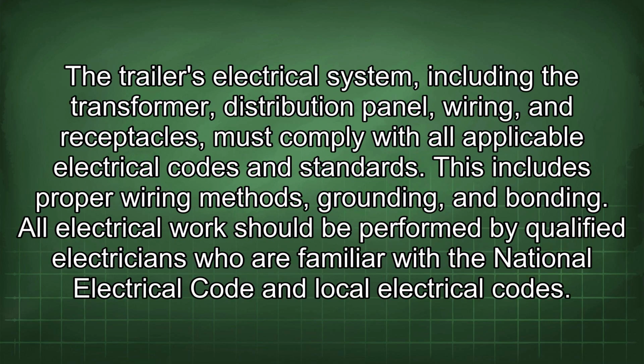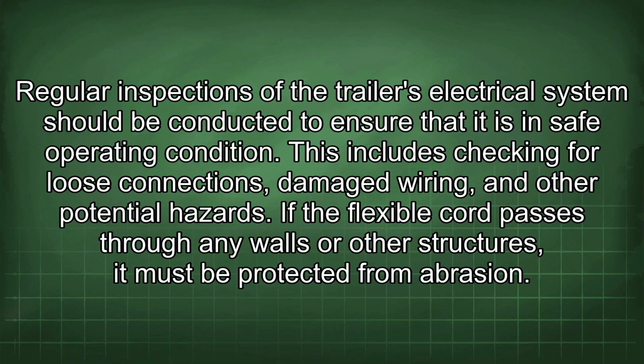The trailer's electrical system, including the transformer, distribution panel, wiring, and receptacles, must comply with all applicable electrical codes and standards. This includes proper wiring methods, grounding, and bonding. All electrical work should be performed by qualified electricians who are familiar with the National Electrical Code and local electrical codes. Regular inspections of the trailer's electrical system should be conducted to ensure that it is in safe operating condition. This includes checking for loose connections, damaged wiring, and other potential hazards.